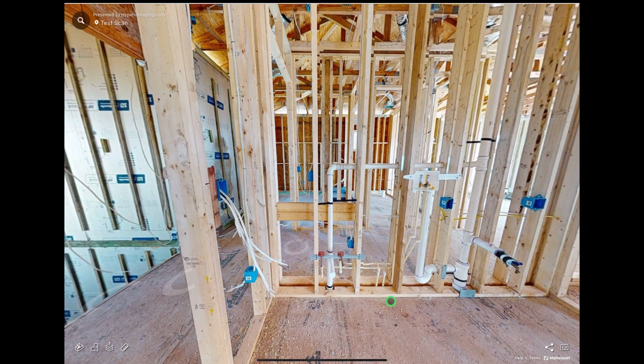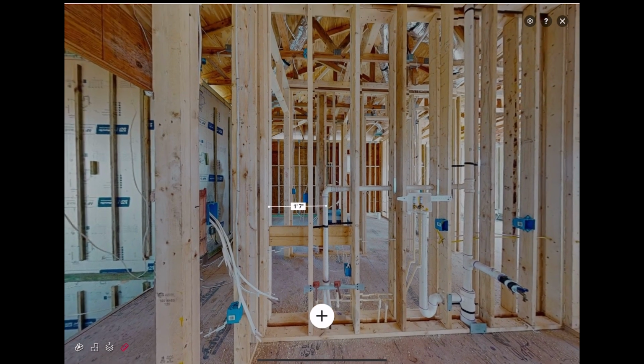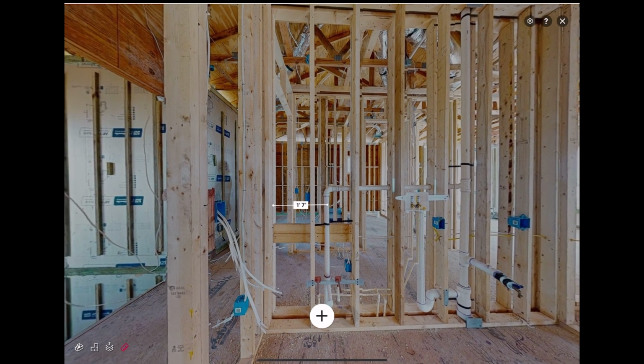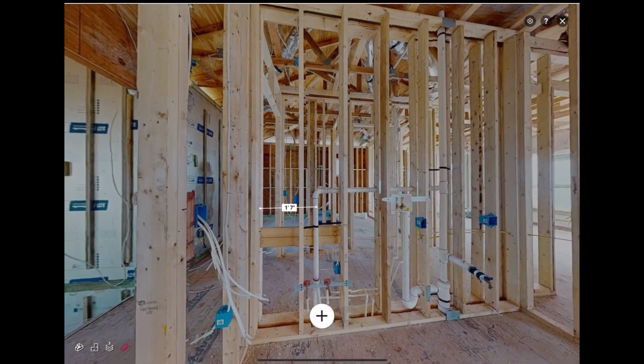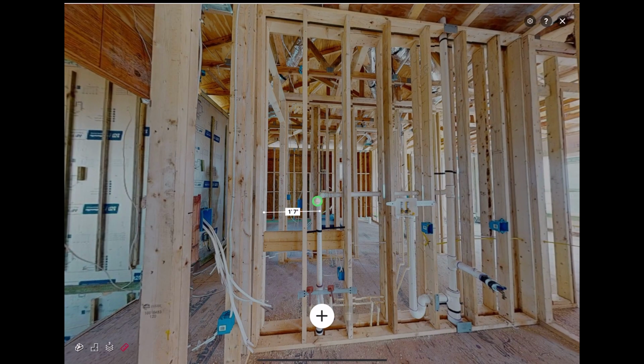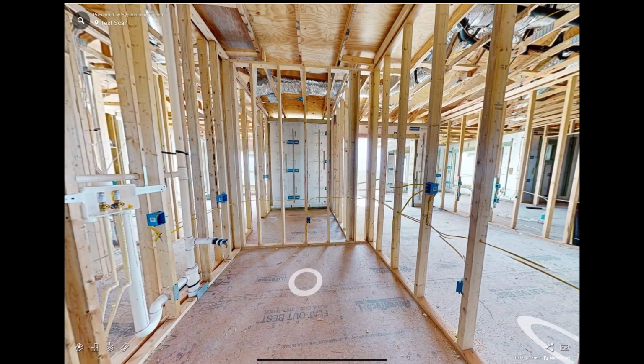This can be very vital when you get into the build and have to fix something or go ahead and put cabinetry in. If there was blocking here, we could see exactly where that blocking was and measure it. Here I've already pulled a measurement of where this plumbing line is in relation to the left-hand wall. This is something that can really save you a lot of headache, being able to document all of that and getting the crew up and running with using these Matterport scans to verify things before they need to start going into the walls. So it's a very, very useful tool, and why it's very helpful to scan a project in this stage. We can see exactly where the wires are and everything.